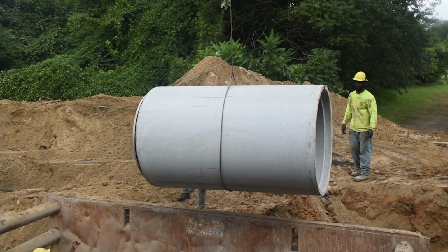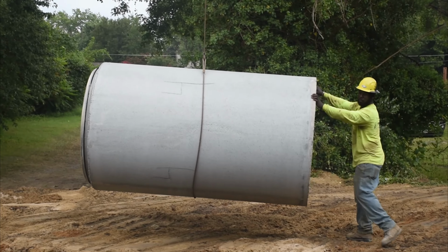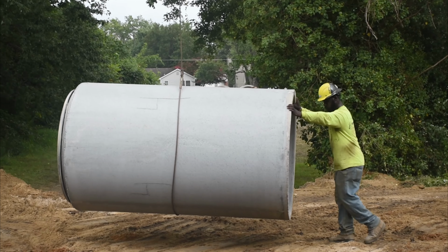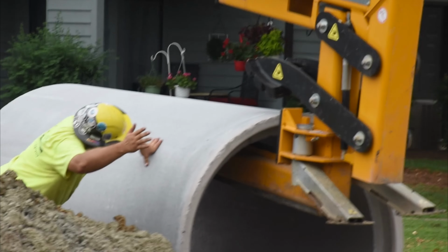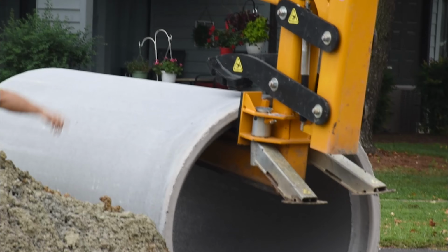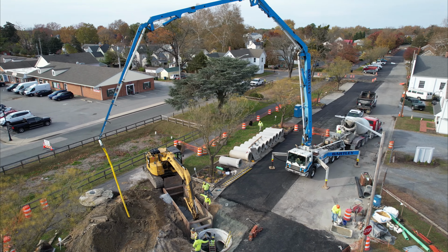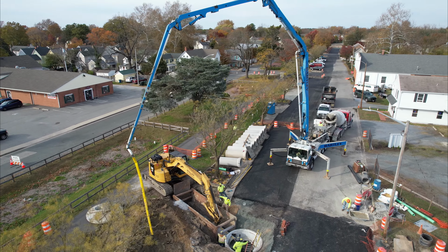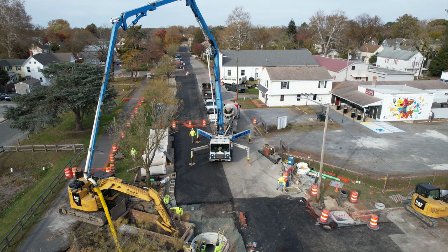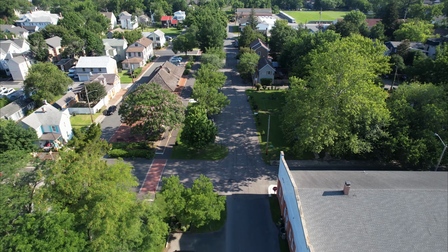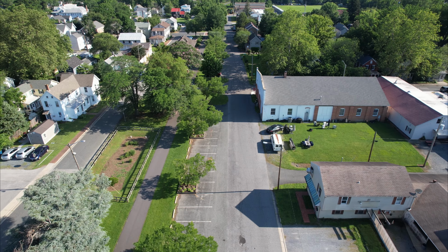Reinforced concrete pipe, or RCP, was utilized for the entire project. Despite being heavier and more difficult to install than some alternatives, RCP was chosen for its durability, strength, and long-term performance. Installed correctly, RCP has a lifespan of well over 100 years. The existing storm drain main was 24 inches in diameter for its entire length. The majority of the new storm drain pipe is 48 inches in diameter. This 48-inch pipe will be able to handle a peak flow from a 100-year storm event.